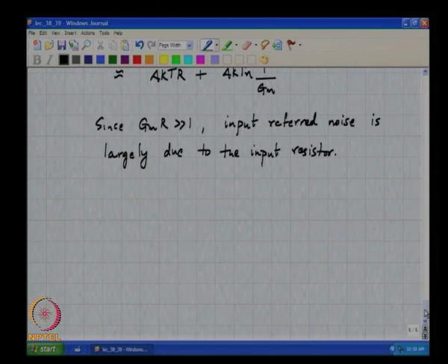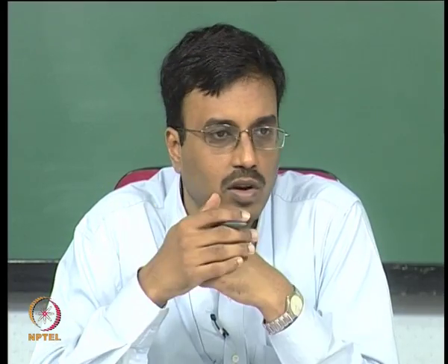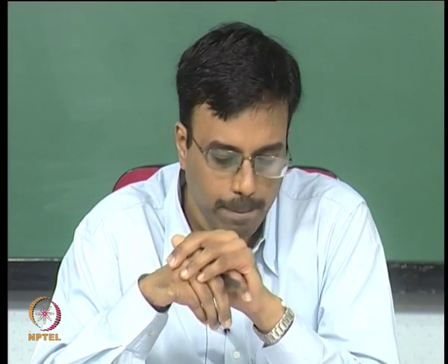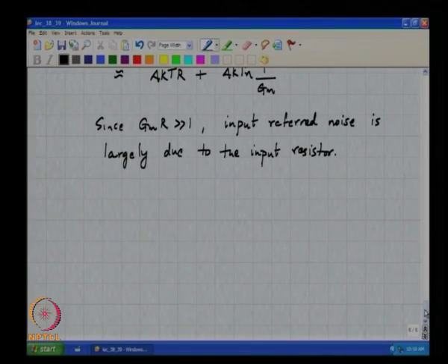Now, let us see, we have now understood what thermal noise does to the integrator. The effect of all these thermal noise sources is a single input referred noise source whose spectral density is pretty much that of the input resistor. Okay. But in our sigma delta modulator we have several integrators. Again, let me take the example of CIFF loop. So the loop filter probably looks like this.